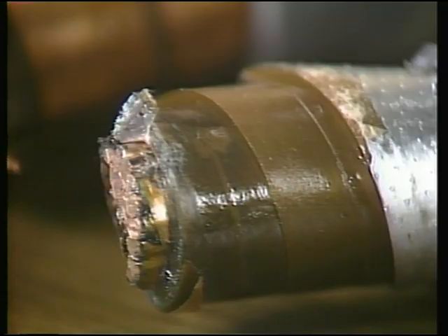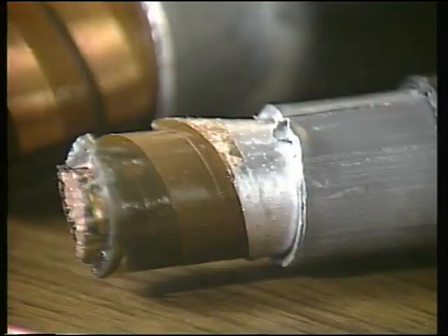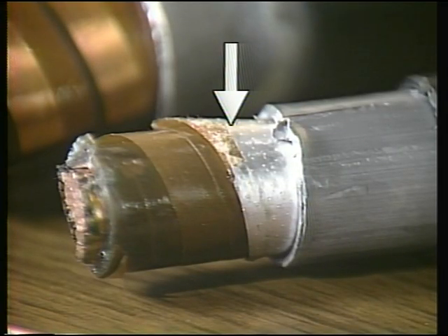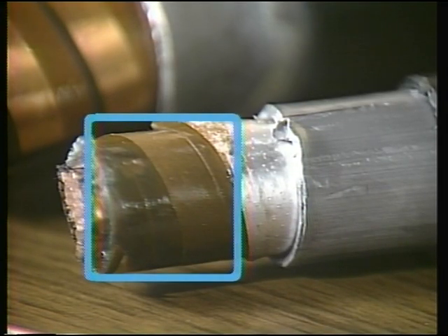To begin with, let's look at the differences between this cable and the other cables we've seen. The basic construction of the cable is similar. There's a conductor shield, insulation, and an insulation shield. But the insulation is made up of multiple layers of paper tape that are wrapped around the shielded conductor.